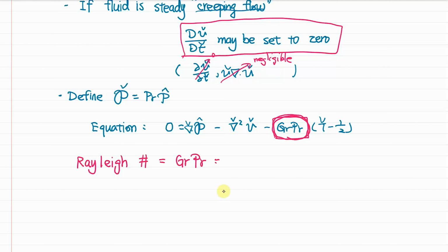And this equals what? Equals rho squared g beta times T1 minus T naught over, there's also the height cubed, Cp over mu, the viscosity, and the thermal conductivity of the fluid. Okay?